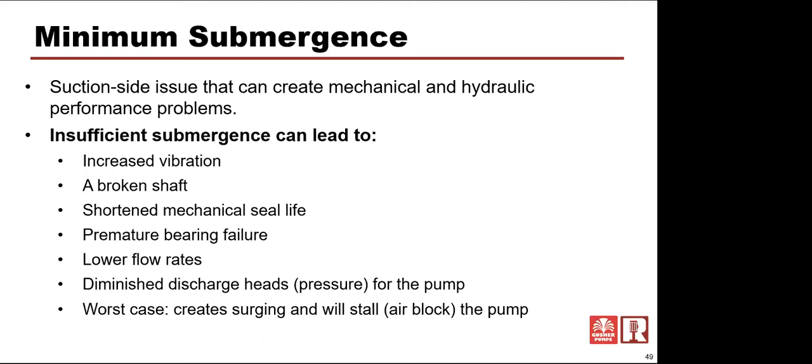And the percentage of air is determined by the volume of the air, but certain types of pump can handle more percentage. Remember that chart that we compared different types of centrifugal pumps? Some types of centrifugal pumps, like say a vortex or recessed impeller, can handle up to 30 or 40% air because of their design. Other types of pumps, like say ANSI pumps, can't handle as much air.